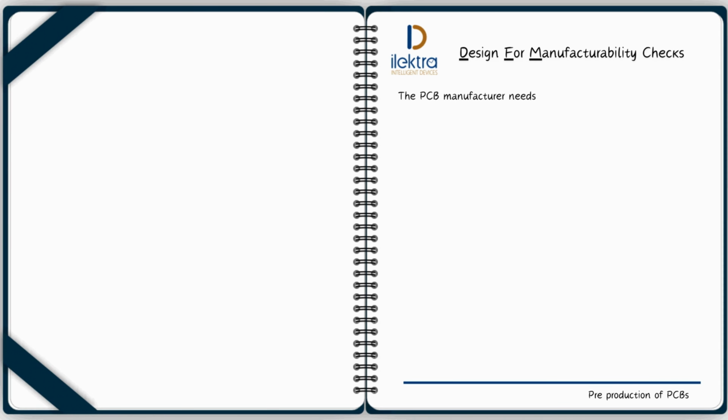The PCB manufacturer needs the following files to produce a PCB. Bill of materials. This file describes the materials to be used for board fabrication. Netlist file that provides the X and Y location of physical net points. Drilling files with hole coordinates and drill size.